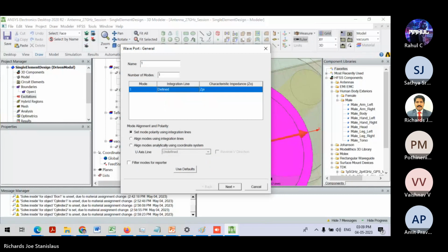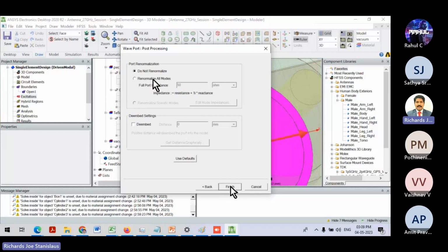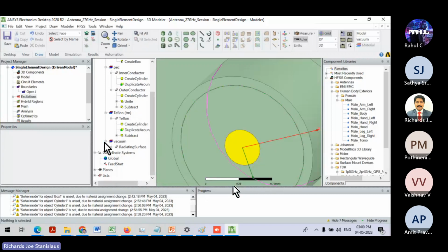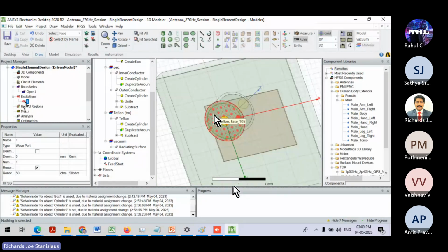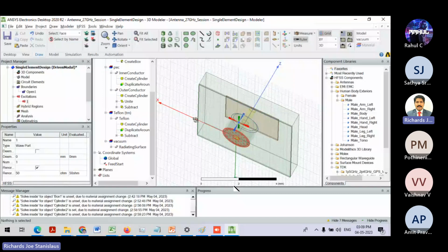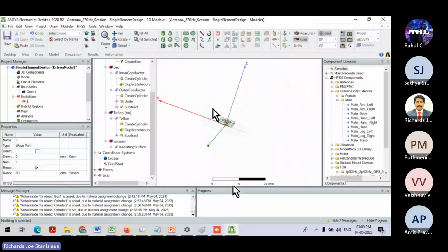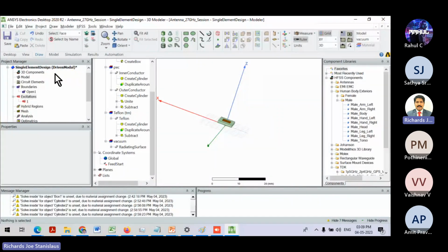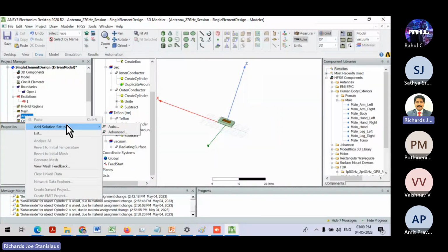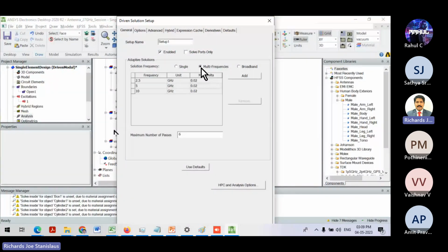Right? Now, click next, and yeah, this gives us the excitation, electromagnetic excitation from beneath towards the antenna, and the antenna is in turn surrounded. So once this block is done, right, all you need to do is take the setup, go to add and create this advanced setup. So what we'll do is we'll initially plot